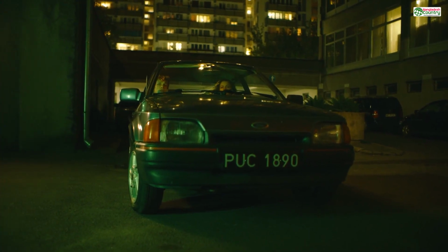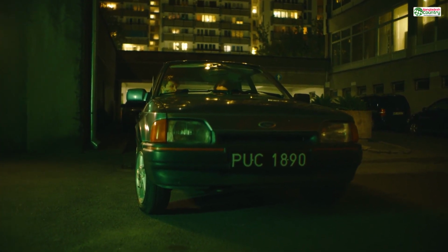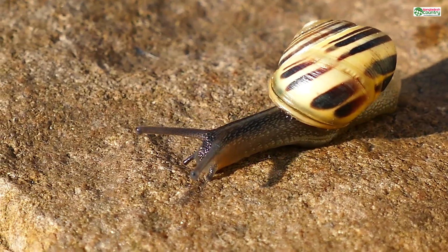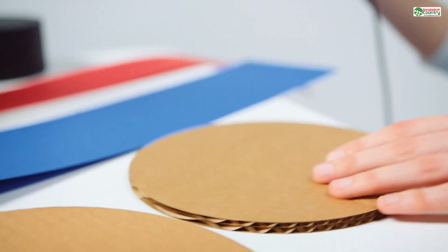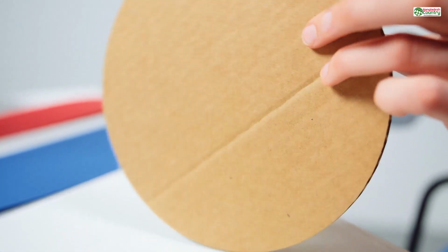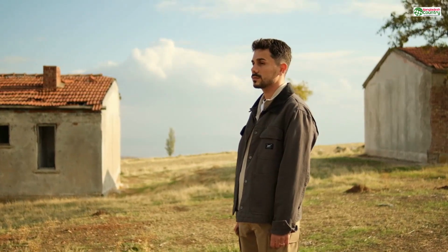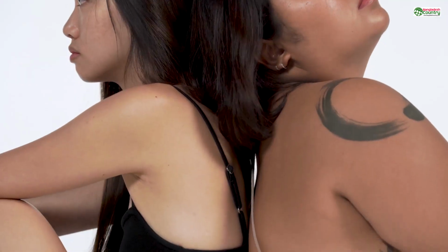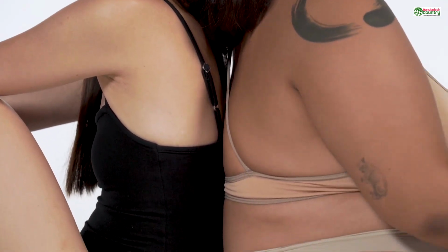So where do you put these holes? In the least conspicuous place possible. On the bottom of a base, on a surface that will be glued to another part, somewhere that doesn't ruin the aesthetic of your masterpiece. The size of the holes is also critical. Too small and thick resin won't be able to drain out or powder will get clogged. Check the design guide for the 3D printing service you're using.